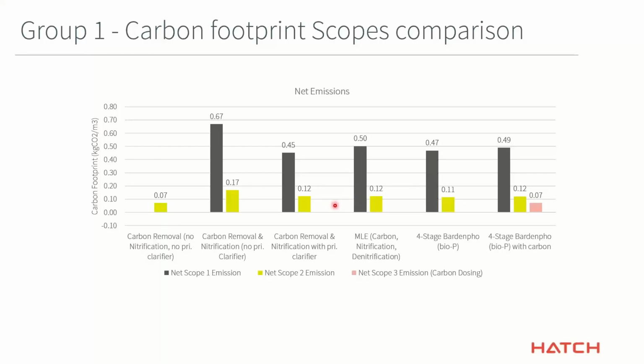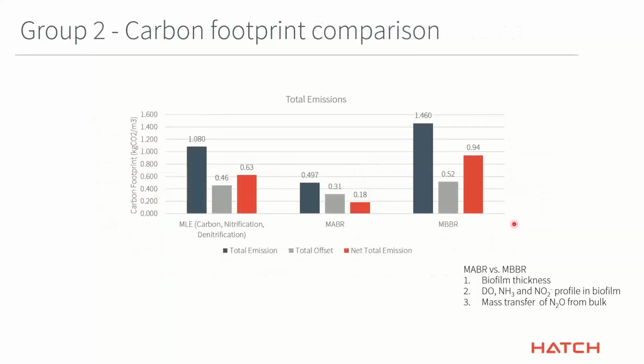In fact, for a denitrification system, since we are using nitrate as an electron acceptor, reducing our oxygen requirement, we actually gain some additional value there. But at the same time, there are some process emissions which are much higher. And if we start adding carbon, then that itself starts to contribute to the overall carbon footprint for these facilities.